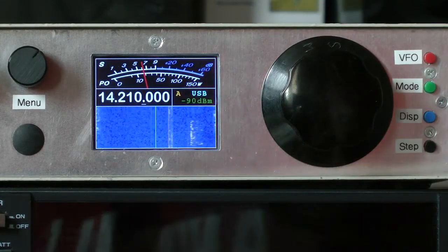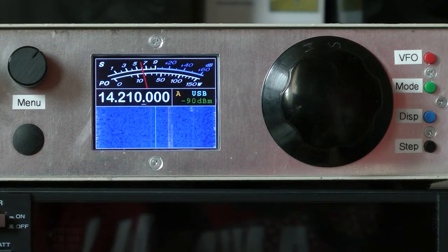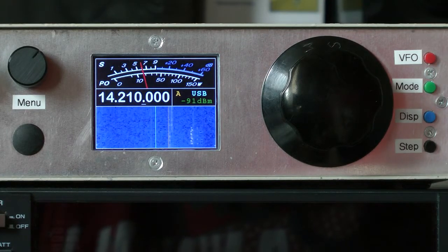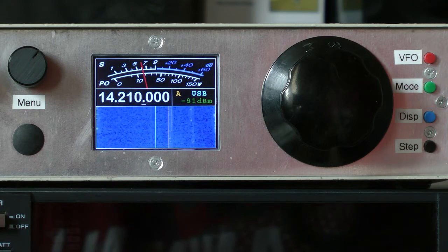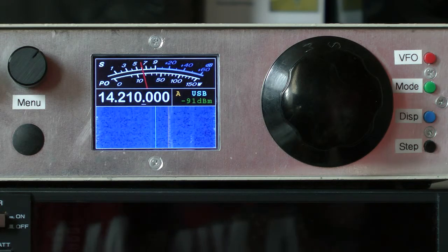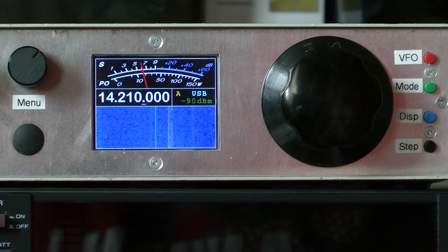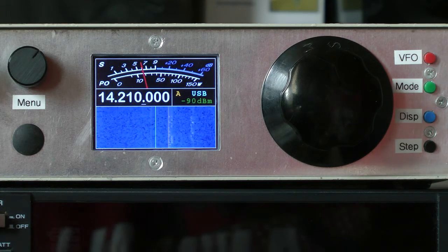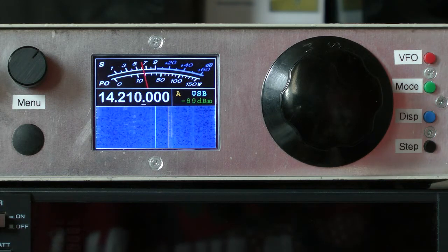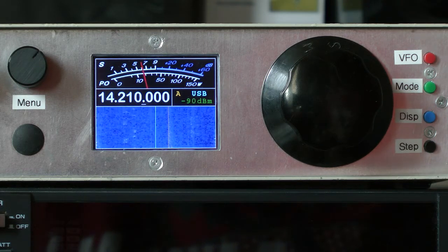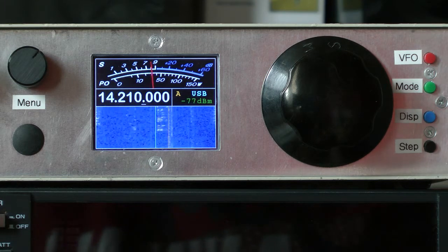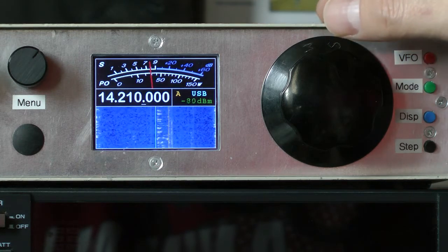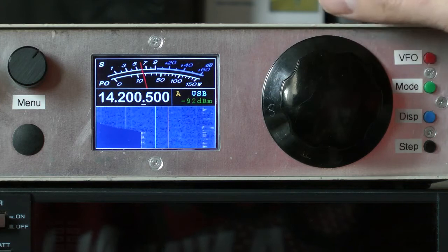Hi. So this is a video to give a quick overview of my homemade HF software defined receiver. It's based on an STM32F429 discovery board from ST Micro Devices, and this has an ARM Cortex M4 processor with hardware floating point and an LCD controller. The receiver is a G0ETP's design, and it has a DDS local oscillator, a 24-bit ADC, delivering I and Q signals at 25 kilosamples per second to the processor.